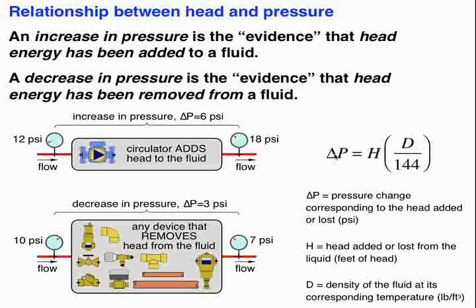So the accurate way to convert between head and differential pressure, you really have to know the fluid you're working with and at least an approximation of its temperature in that system. Let's say its average temperature. Okay?